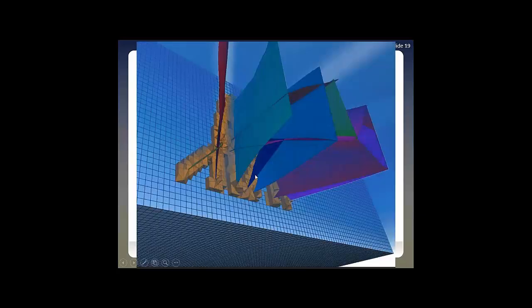And here's the nice view in the FLAC 3D model after we translate. You can see in detail what happens. We have a stair-step mesh that has remained unharmed. These surfaces and the boundary of the stair-step mesh, the volume in between, has been meshed with very handsome-looking tetrahedra that, by the way, incidentally match the grid points.